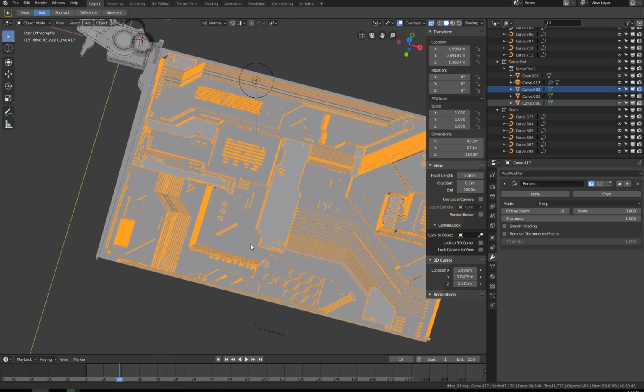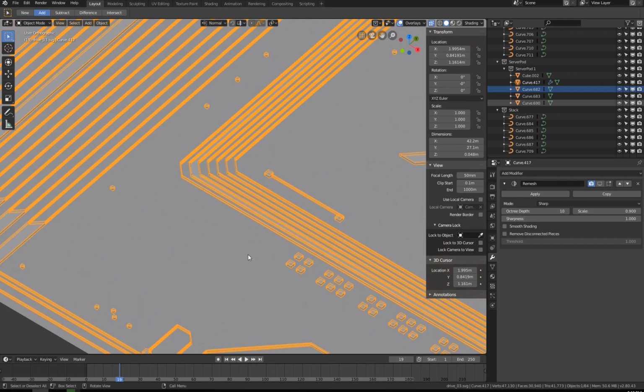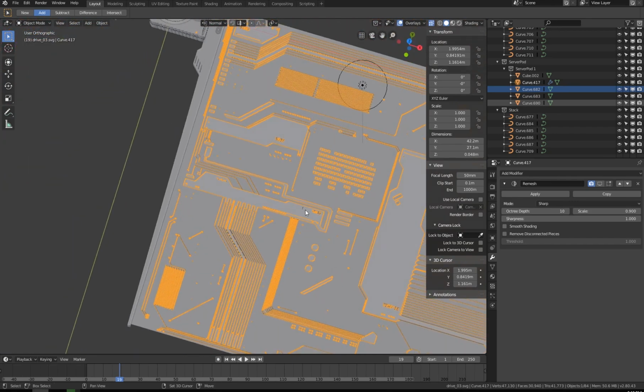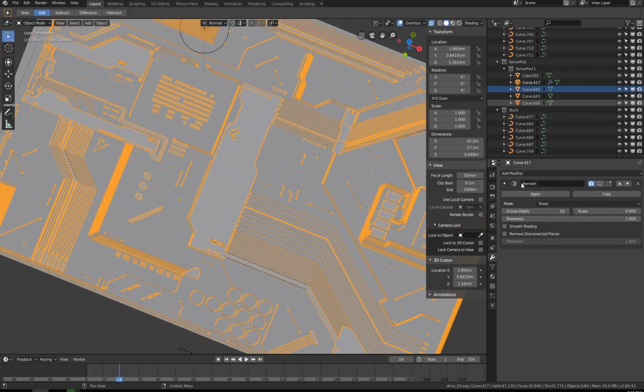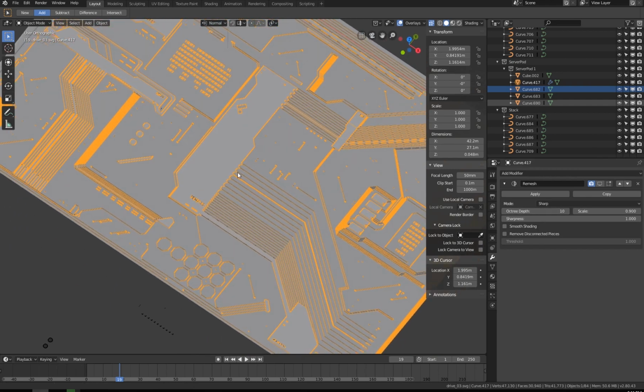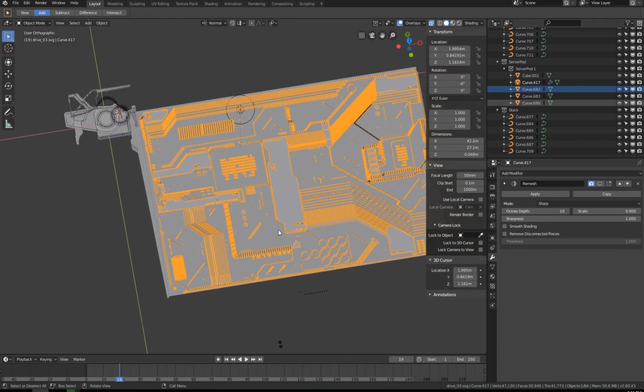But the thing is that when you create graphics from vector inside Blender, you get a pretty dirty mesh that's not really easy to boolean through. It gets you a bunch of artifacts, so you have to do a remesh operation. I actually have it here. And remesh has to go really high, so it's not activated right now, but remesh is at Octree depth 10. 10 means it's going to be like a million polygon mesh, which is really easy to boolean because everything becomes quads, nice quads. But it's so time consuming just to run the operations, run tests, and I was running out of patience, wanted to wrap it up.